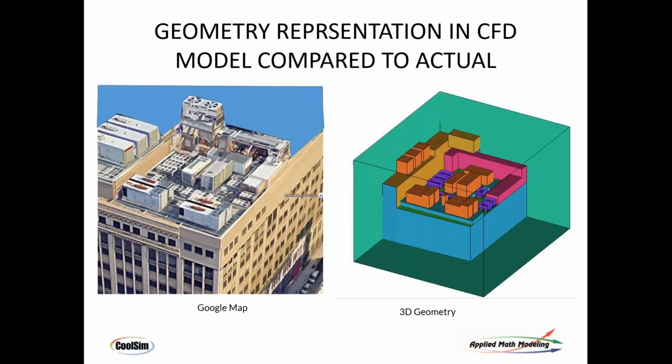This one is one that many of you will be familiar with. This is what we're faced with in today's environment. Here it is. It is the top of a building that is just jam-packed with stuff. Now, not all that stuff is yours. If you're out there doing design, you know that that roof is being shared by a lot of different vendors, a lot of different people, a lot of different stuff going on. You see generators here. These are auxiliary generators that are being used in the case of a power failure. Cooling towers over here that are being used to dump heat. And these are what we call dry coolers. Dry coolers are typically a chiller with a dry cooler that's dumping heat to the atmosphere. So very, very crowded rooftop.